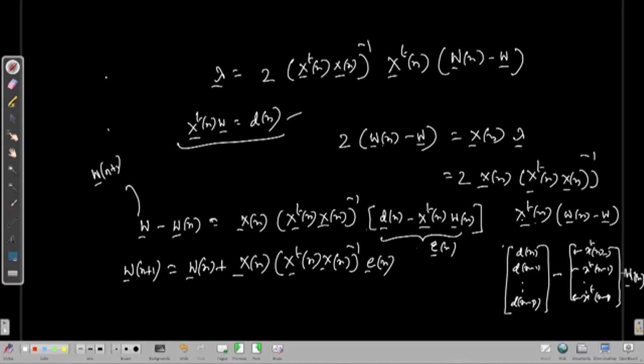But now suppose I use the same filter coefficients, but take a look back. Suppose I go back and use these coefficients only, but in the previous clock n minus 1. That time my input data vector was X n minus 1. So, the filter output with these coefficients will be X transpose n minus 1 w n. If I subtract that from d n minus 1, that will be the next component of error.